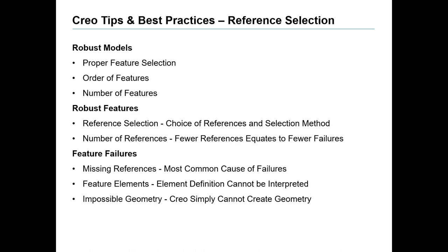Well, that's not always the best approach. You don't want to put too much in any one feature because it becomes difficult to modify when we do that. So, try to be a little bit thoughtful of what you're putting into any given feature.